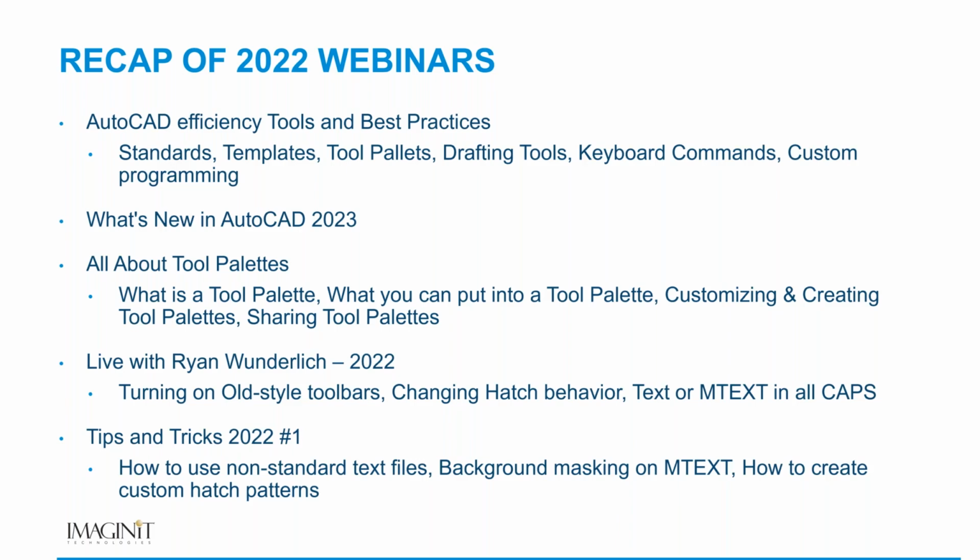And how do you work with other templates and save it as a template? Usually I'll open up the template. So I'll open the DWT directly, not start a new drawing with it. And then I will make my modifications and then I'll save as and save it as a template, as a .dwt, Paul.